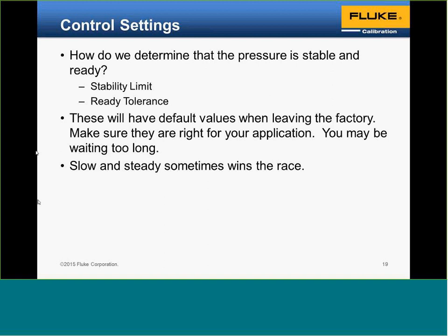A very good setting is also resolution. If the pressure on the front panel is displayed at too fine a resolution, it'll seem like the pressure is never stable, because you're looking at digits that don't matter for your actual calibration. So make sure you've got the resolution set properly for the application, for the calibration you're performing.